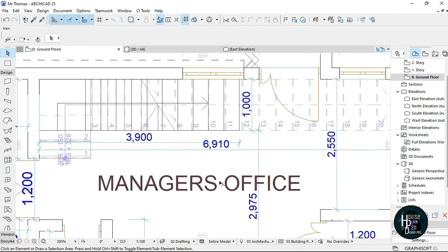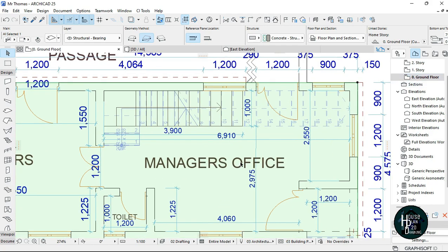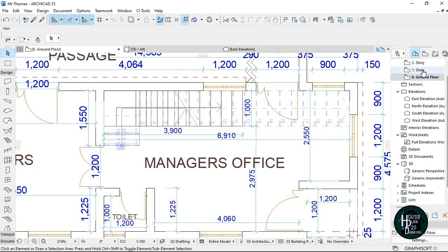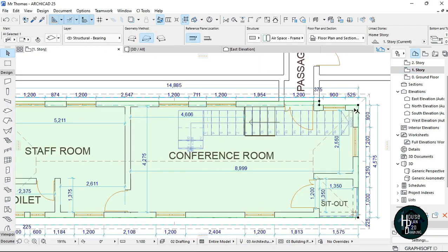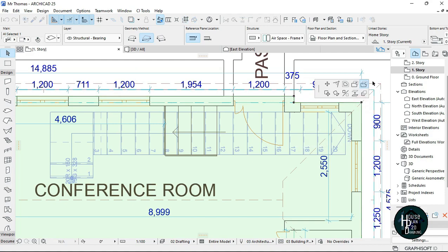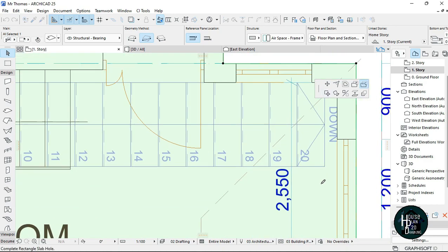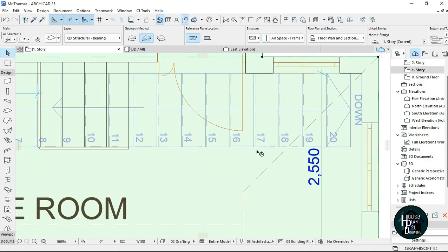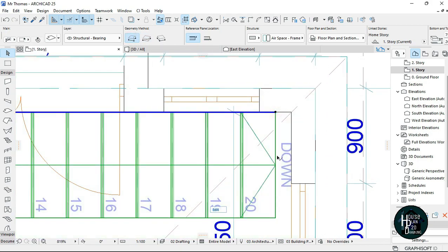To open the step, you can click on the slab tool. Okay, this is the ground floor. I'm supposed to go on the first story. So when you click the slab, click this node here. Now click this subtract from polygon. Now trace out the side you want the step to be seen. Trace it out. Make sure you are selecting this. Trace it out like this.